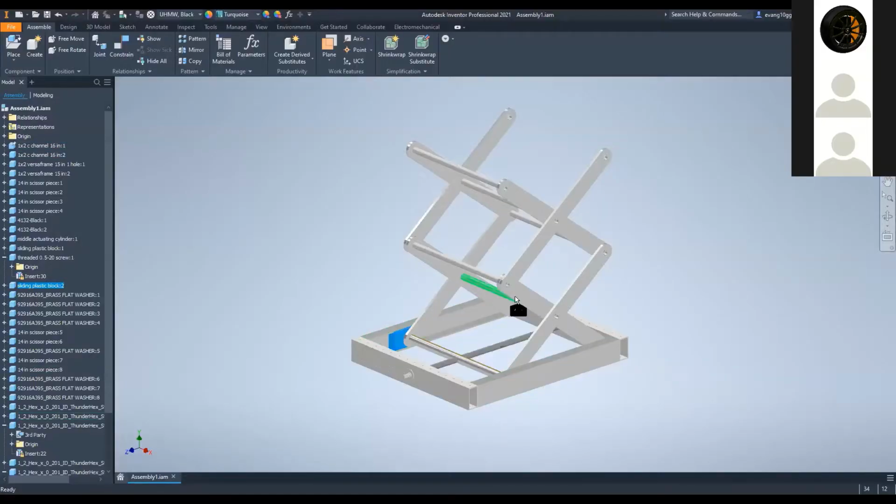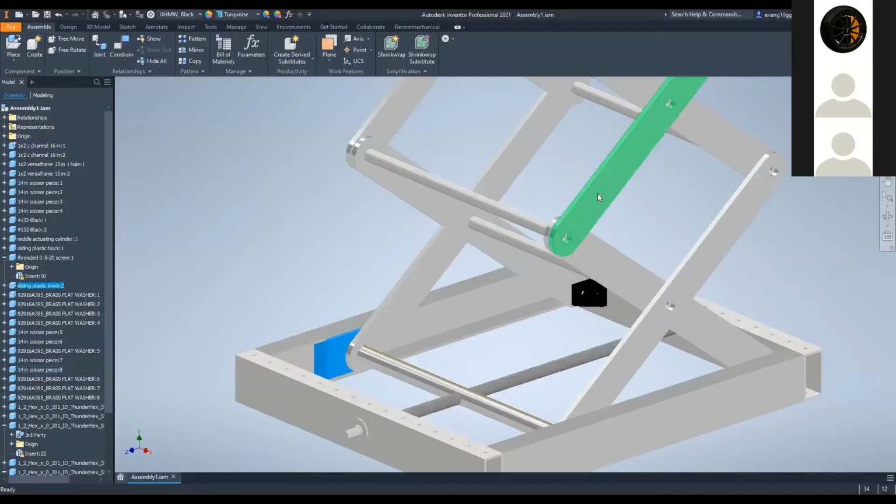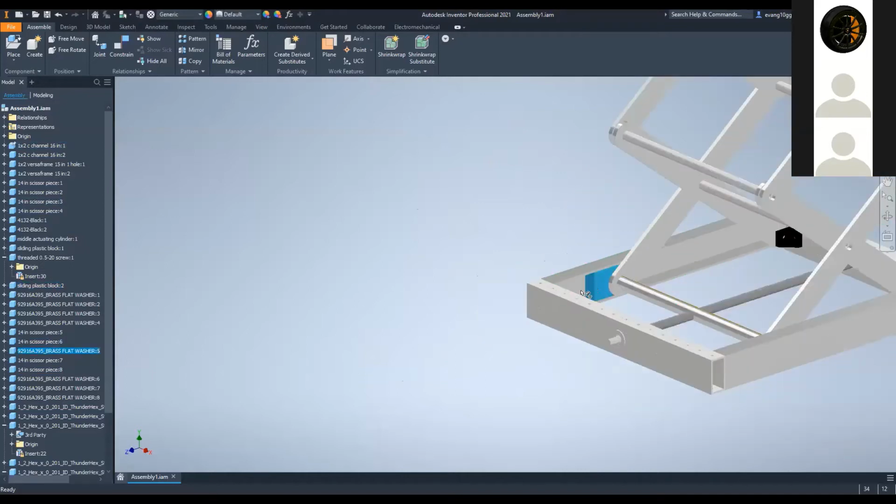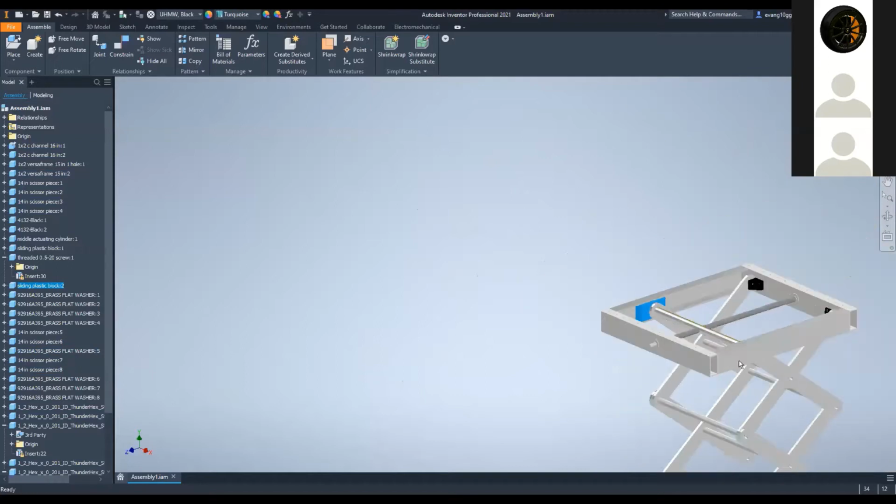I had a quick question about angle constraints. Yeah, here, I'll screen share so you can see the problem with it. I don't actually know what the problem is, but all these angle constraints that we did allow a mirrored image of this to also work with the constraints. So if you pull this bottom block too fast, it just flips.